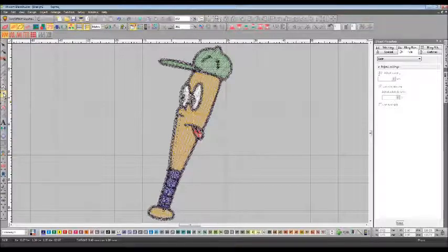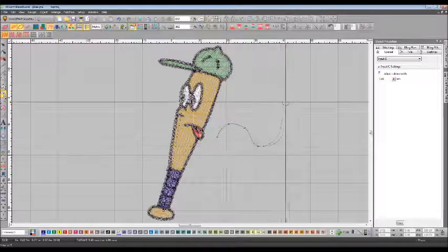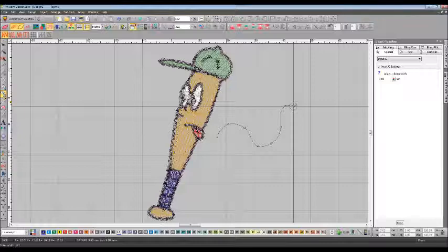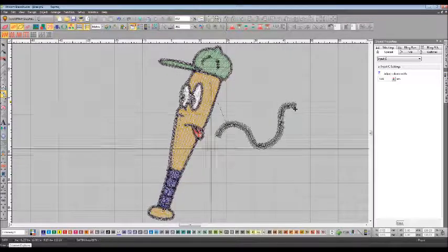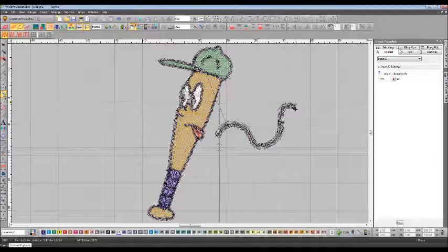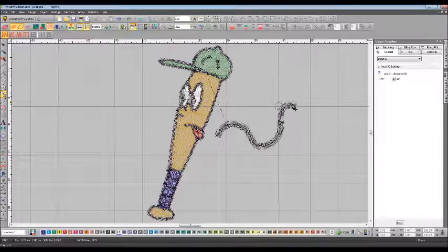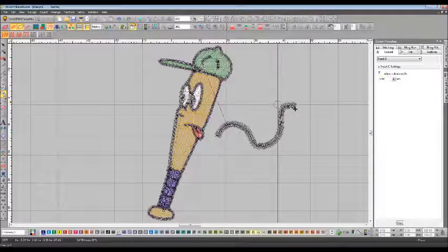Let's talk about that real quick. Input C allows you to digitize one line, hit enter, it asks you for a width, 0.1, 0.2, and it's a single width column stitch. Great for automatically digitizing outlines around objects very quickly.